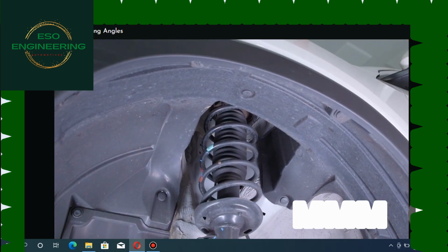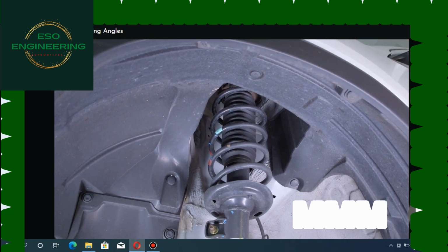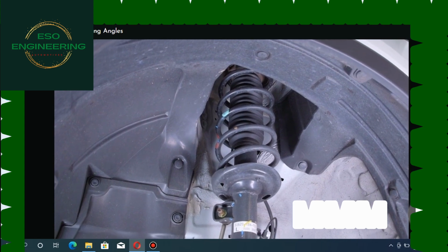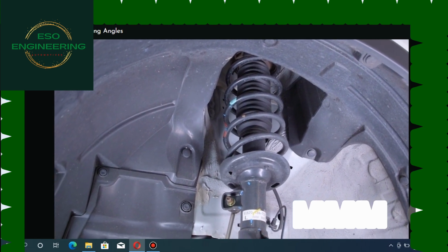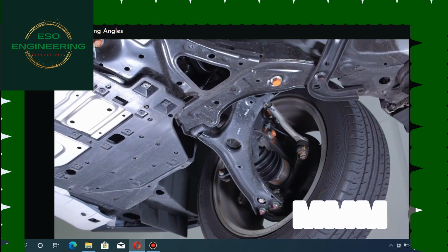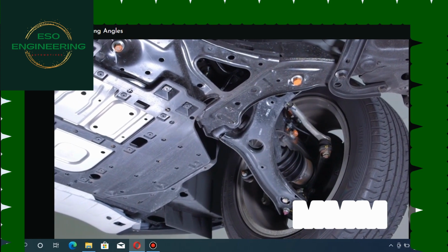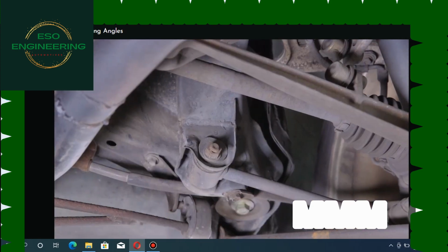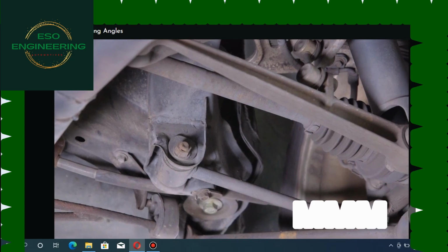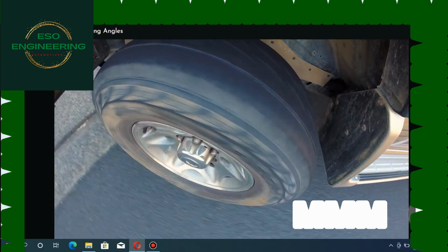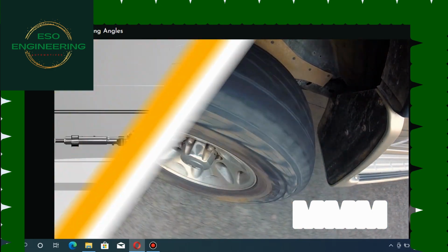The vehicle's SAI is a pure diagnostic angle. It can be used to detect damaged or misaligned strut towers, or a shifted cross member, or bent control arms and stub axles. If SAI angles are unequal, it may cause torque and bump steer, or even brake pull.